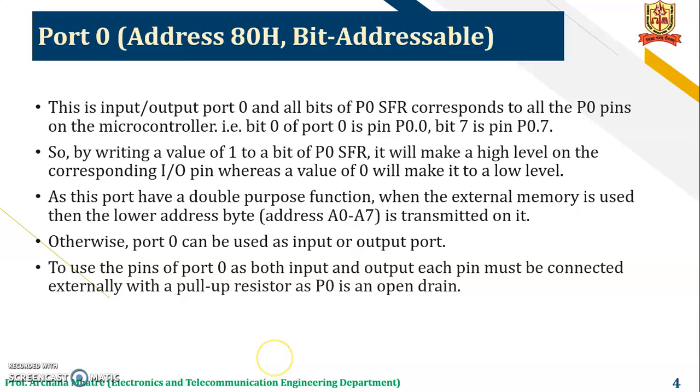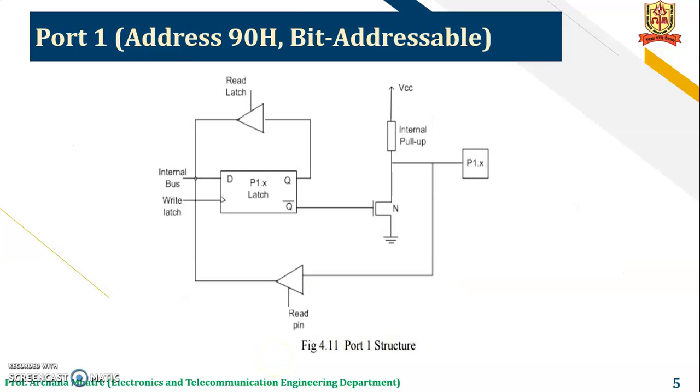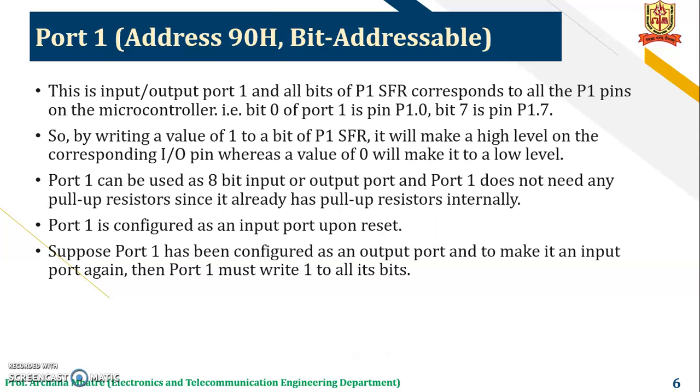Now next is port 1. Now this is the port structure of port 1. It is an 8-bit port and it can be used as an input or output port. The address of the internal RAM location of this port 1 is 90H. So this is the input-output port 1, and all bits of port 1 SFR correspond to all the P1 pins of the microcontroller.